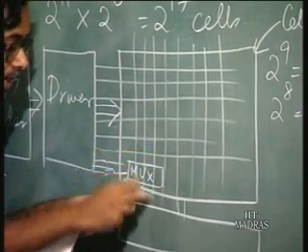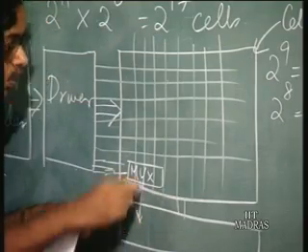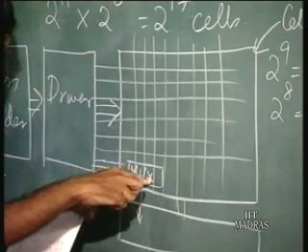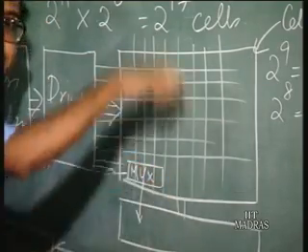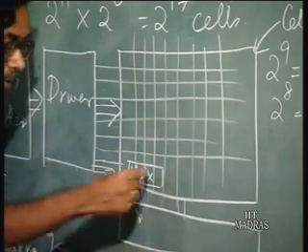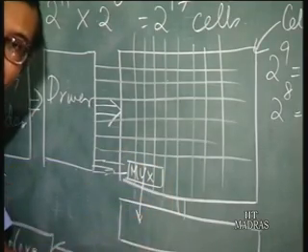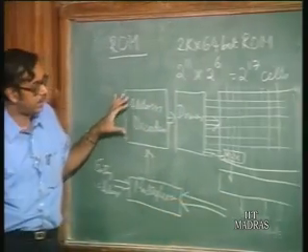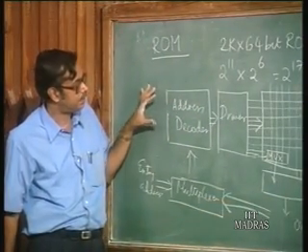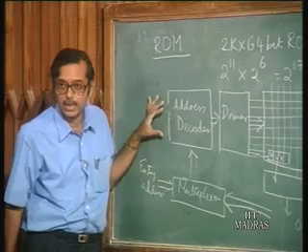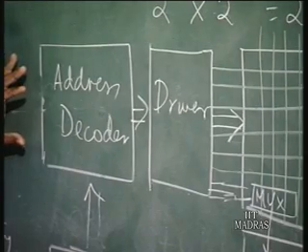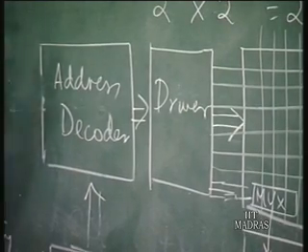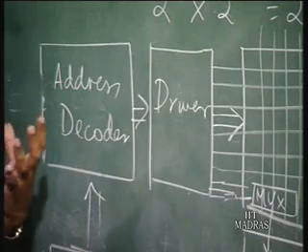The output of that multiplexer is one of the 8 columns. So, you have 64 into 8 columns, and the output which you get here is 64. Again, just to repeat, you have 2 to the power 11 address lines, 2 to the power 11 locations, okay, addresses, each going to have 64 bits of data.